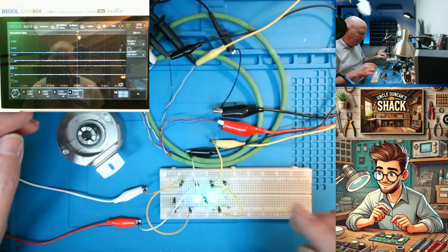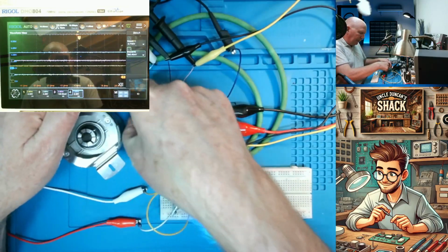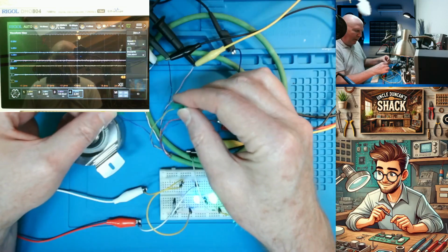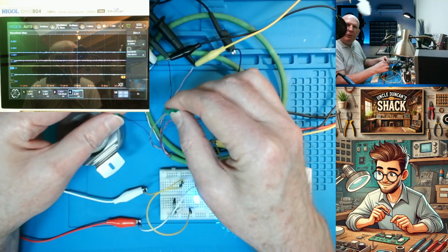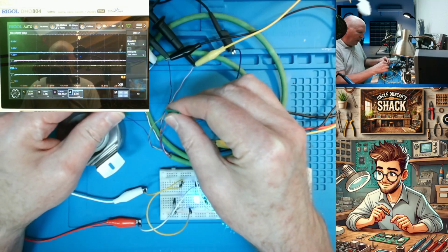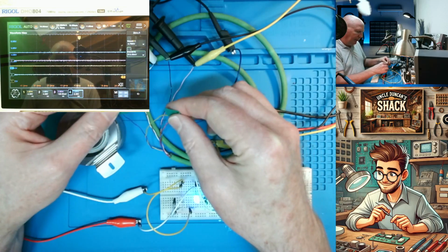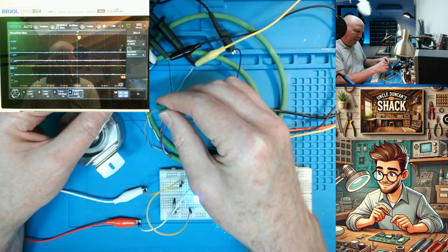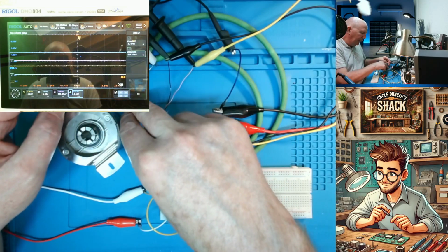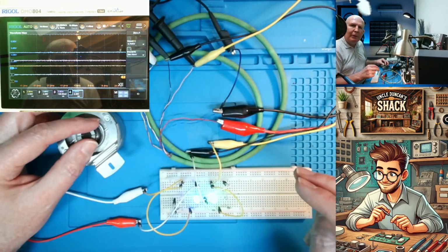Okay. Now, I've got two taped up wires over here. That is called a marker. Okay, that is 1 pulse per revolution, and that is 1 pulse at the 0 degree mark. It's also a differential signal. Okay, so that indicates 0 degrees on the encoder.